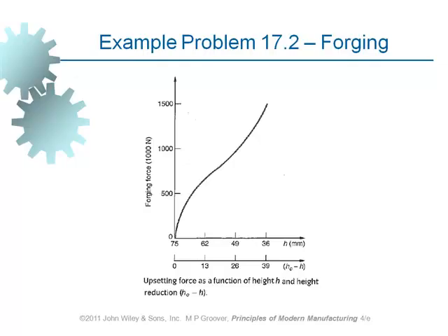It is maximum at the very end of the process. So in the forging process, force begins from minimum, increases significantly, and reaches a maximum at the end of the motion of the die. When it is moving down, at the very end, we need the maximum required force.